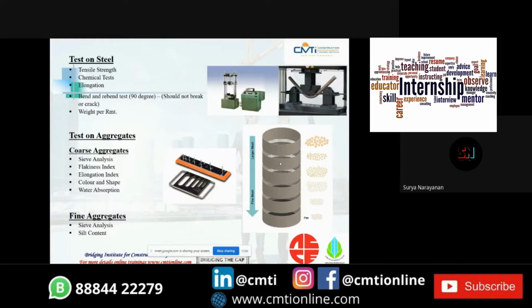So next is tests on steel. Tensile strength, elongation test, and compression test are tested in the labs, where we use universal testing machines, as you can see in this image. Bend and rebend tests are also done in the field, where the steel should not break or crack. Weight per RMT is also checked in the field.